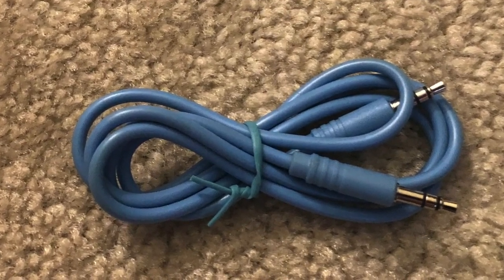So I plugged the converter into the headphone jack. I plugged my 3.5mm cable into the converter and then ran it to one of the GoPros and plugged it into the audio adapter. And it did capture the audio. However, what I didn't realize was that that cable was unshielded and that there was a lot of electrical noise in the audio system that I couldn't hear over my headphones, or certainly I'm not even sure they were actually in the headphones, but the GoPro picked it up completely.